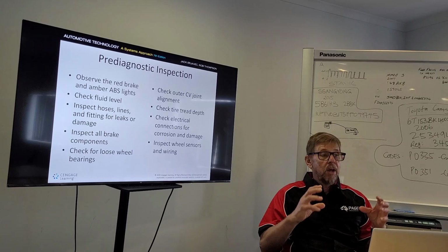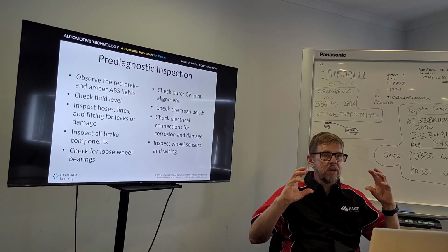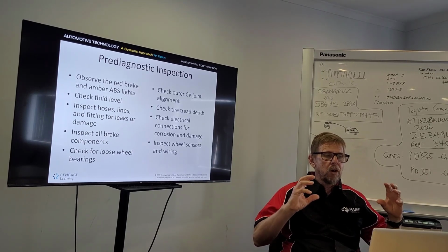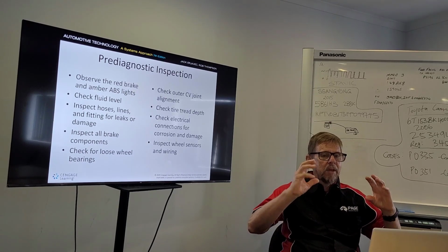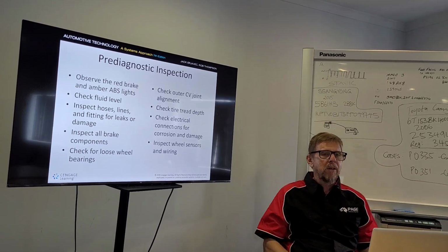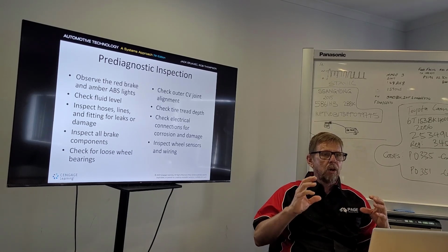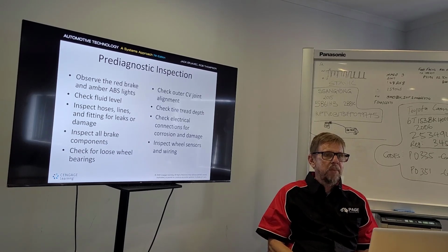We're talking about keeping the tyres fairly even so that the ABS traction control, if something goes off, will pick up on the different wheel speed and try and rectify the problem. But if we've got a low tyre or baldy tyre, we're going to have more slipping in that tyre, aren't we?